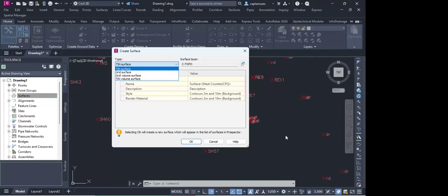So this space here, since we don't have anything here, this point will join to this one, and then to get the approximate elevation for this area, that triangle will be used to estimate. So if this point is 620, this is 630, and this 640, if we are close to this point, it's more likely to be close to 640 than 630. And that's how it's used to compute.